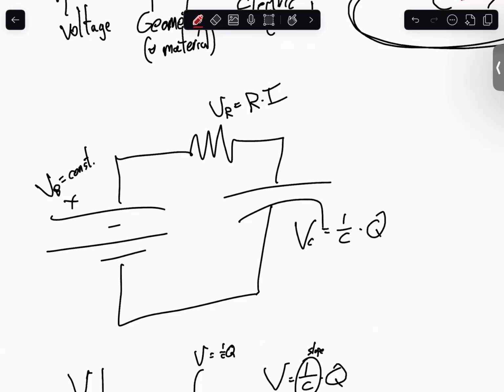So this capacitor approaches asymptotically, as we say in mathematics, approaches but does not ever theoretically quite hit, the battery voltage. It's always increasing, but at a smaller and smaller rate. As the resistor has less and less voltage, the current is less and less. Never 0, but accumulating charge at a smaller and smaller rate. Now, turn to your neighbor and tell them this story. It has 5 parts. You gotta think about it.